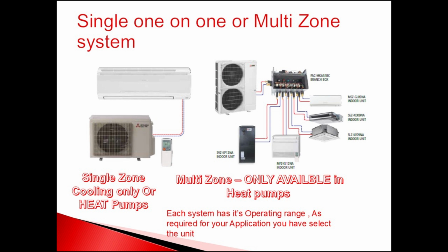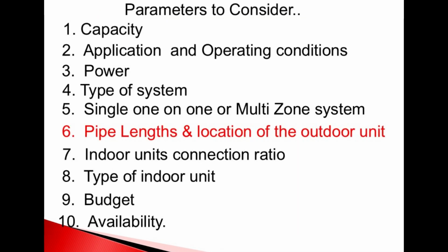For multi-head systems under 5 tons, you can operate either in cooling or heating mode, but not both simultaneously. For units 6 tons and above, VRF systems offer the capability to cool and heat different zones simultaneously, which I'll cover in another video. Pipe lengths and the outdoor unit location are important considerations when selecting a split unit.